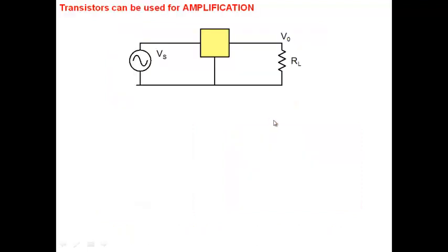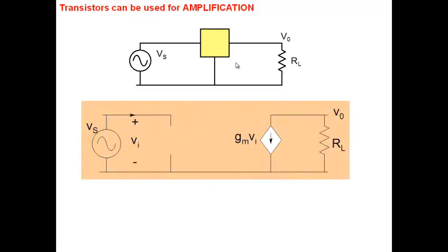All right, and we know that if you have an element like this, you can very easily make an amplifier. Apply the voltage that you want to be amplified, connect a load, take this transistor and replace it by its equivalent circuit, a very simple equivalent circuit, and it's straightforward to see the gain is equal to minus GM times RL. All you need to do is connect, for a given GM, an RL of sufficient magnitude, and therefore you get a voltage gain. We can also see that you'll get a power gain because there's hardly any power going in because of the open circuit, so you're not drawing any power from the signal source, and of course you're delivering power to the load, so you have a power gain also, right?